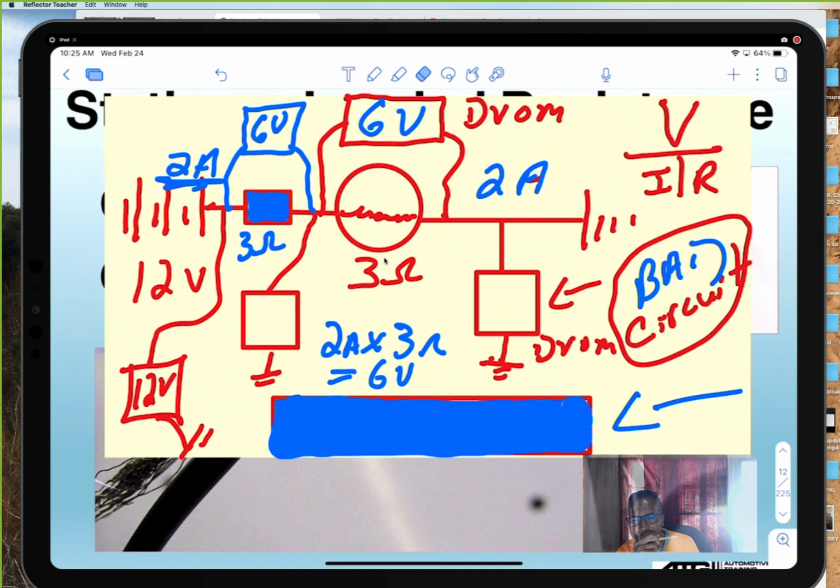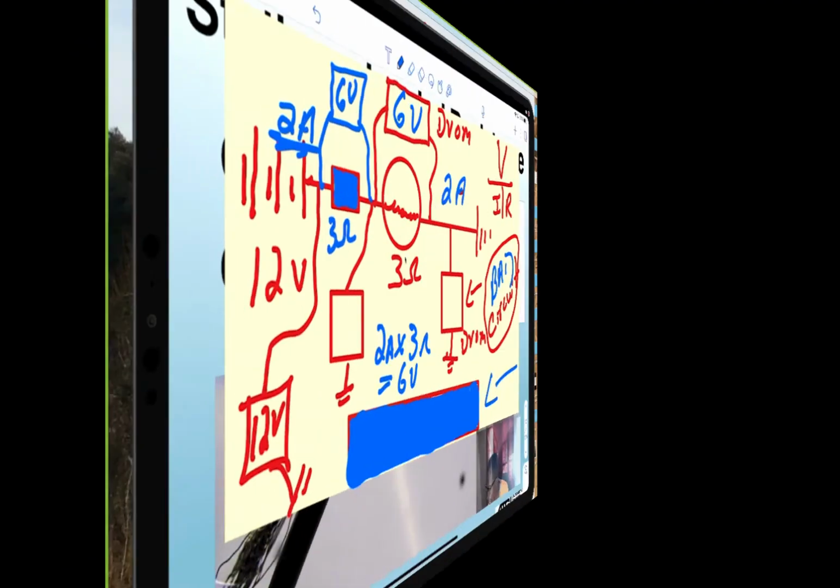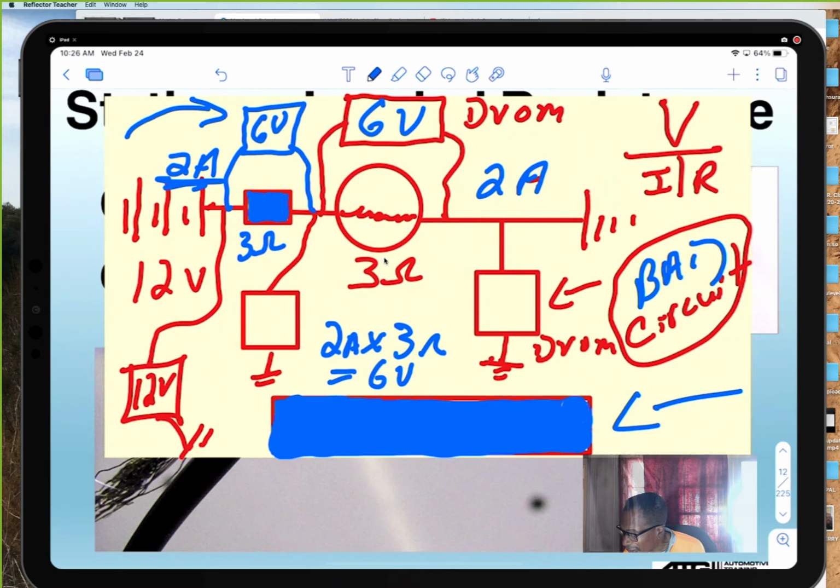Where that insulator's at, there's a false contact. Yeah, you're right. Why is it 6 volts there, and it's supposed to be 0? Across any connector, you're supposed to have less than 0.2 volts, and I got 6. Because there's an incorrect connection. That's correct also, but why? What's that term? Why is the 6 volts there though?